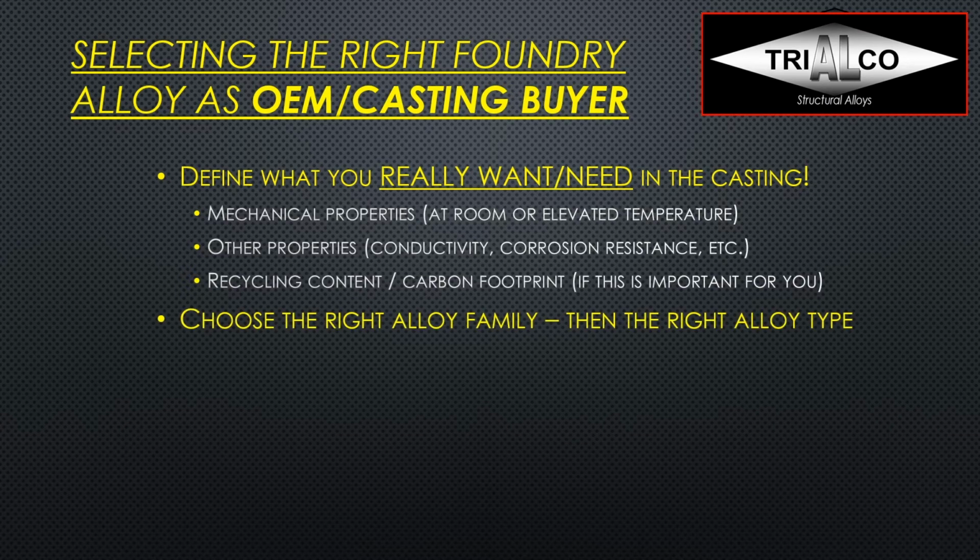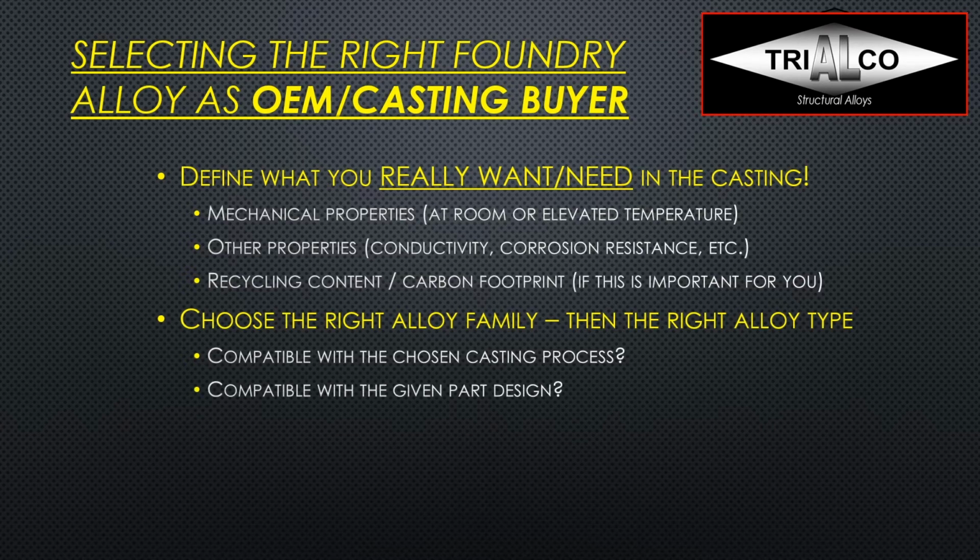And then choose the right alloy family first, and then the right alloy type if you have to. It needs to be compatible with the chosen casting process, of course. If not, then you have a problem. Then you have to go back and adjust, and either choose a different casting process or use a different alloy. Then, of course, is it compatible with a given part design? Because depending on the alloy, you might get all the properties that you need, but it will be nearly impossible to cast, let's say, a very complex, intricate design.